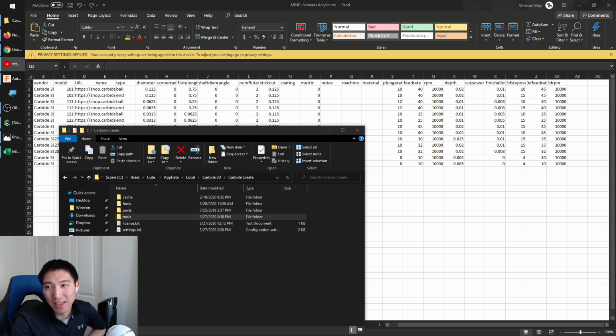You can be that aggressive, but I've found that when you're taking such large chips, there's a lot of heating that happens as you're ripping the aluminum apart. And so that would work a lot better with a mist cooling system or air blast. But for really short durations, if you've got your stock held really solidly in a vise or clamped down, you can pull it off.